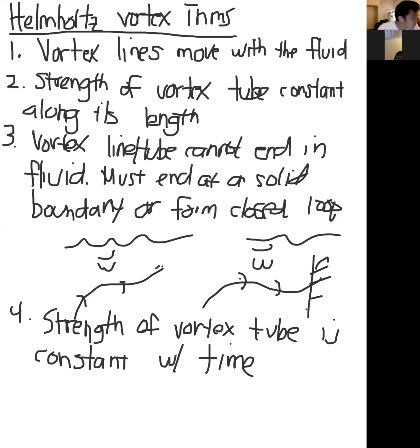One thing I should mention about the Helmholtz vortex theorems is that because they're based on Kelvin's circulation theorem, the same assumptions apply. We're going to assume that the fluid has no viscosity, that the body forces are conservative, and that the fluid is barotropic. So think of the Helmholtz vortex theorems as an extension of Kelvin's circulation theorem.